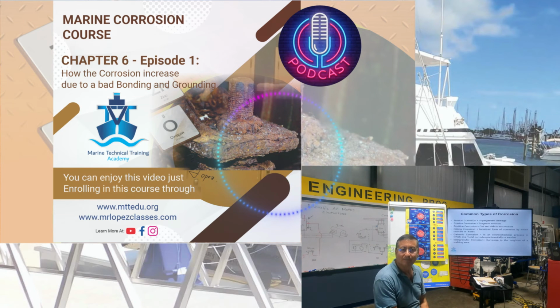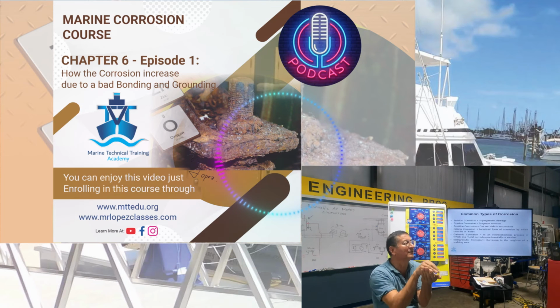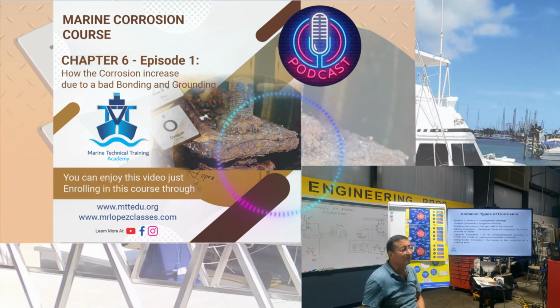Hi everyone. Today I am going to explain the main difference between the galvanic isolator and the isolator transformer. The function is completely different. If you remember, in other videos I explained the procedure to verify if the galvanic isolator is working properly. Basically, the galvanic isolator is inserted in the ground line.